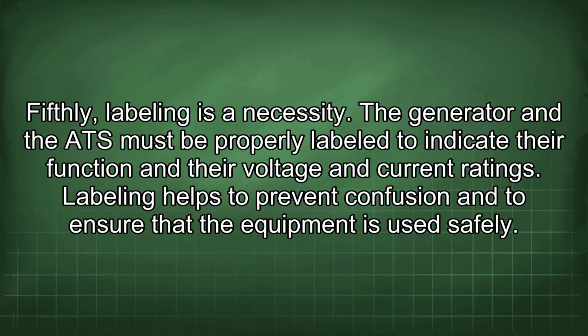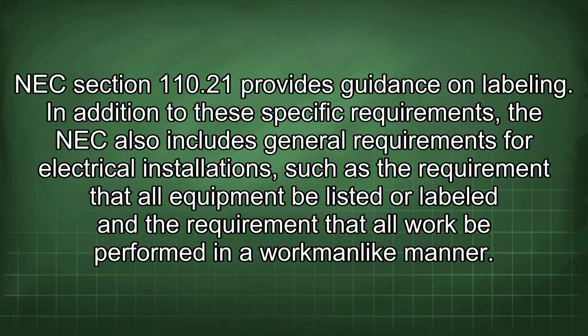Fifthly, labeling is a necessity. The generator and the ATS must be properly labeled to indicate their function and their voltage and current ratings. Labeling helps to prevent confusion and to ensure that the equipment is used safely. NEC Section 110.21 provides guidance on labeling.